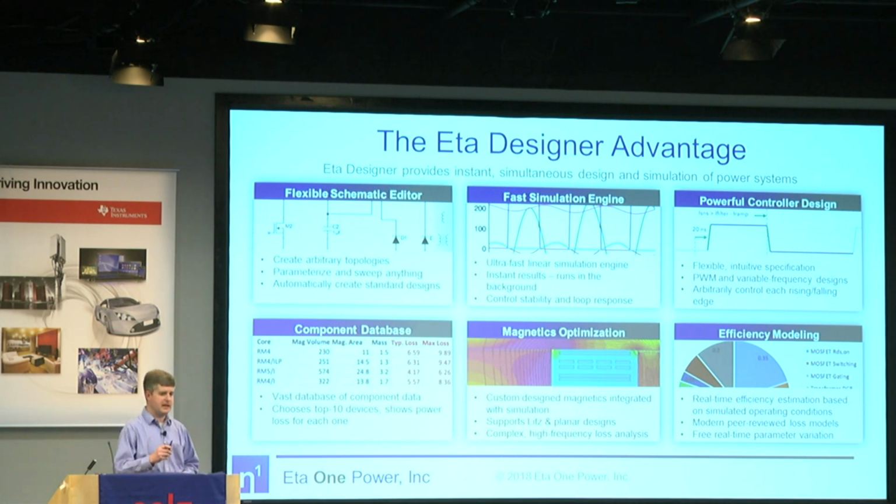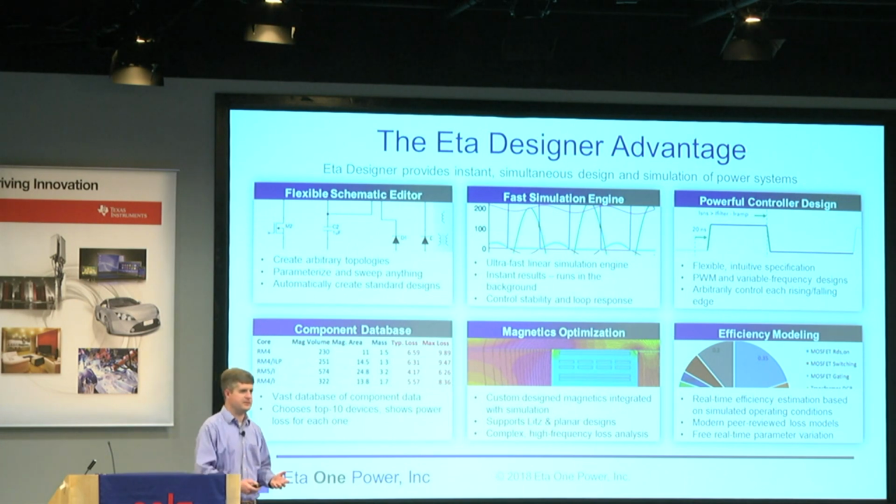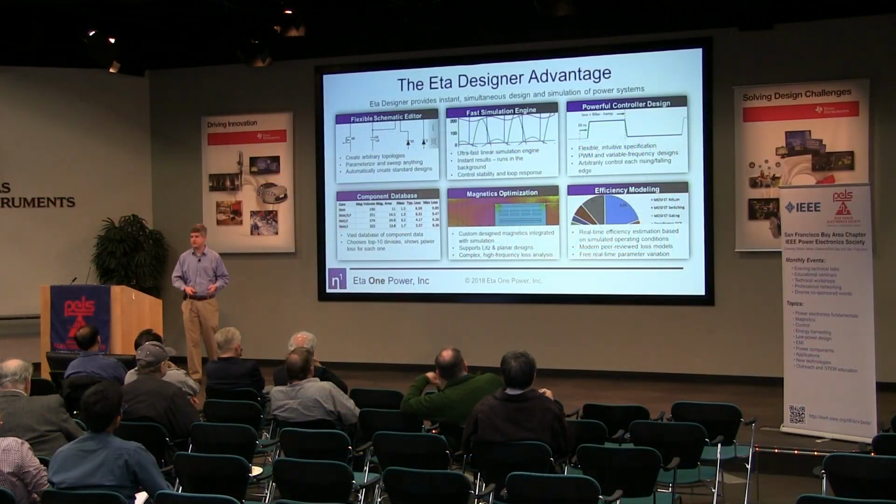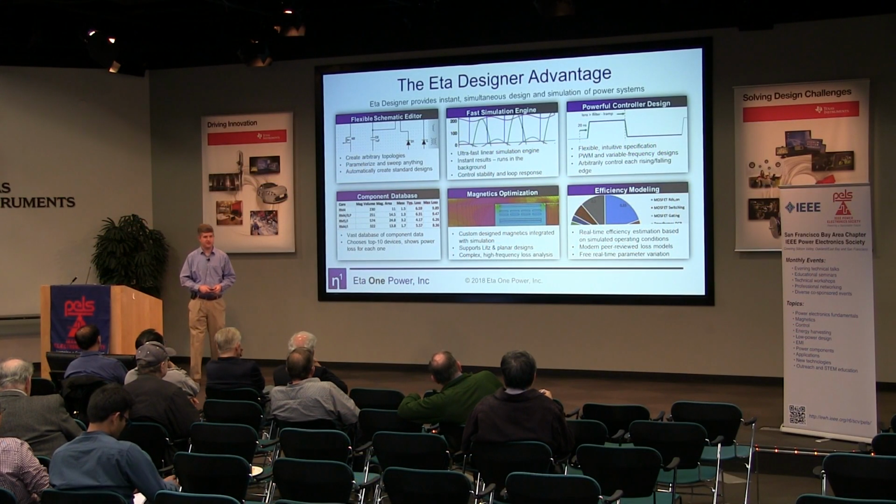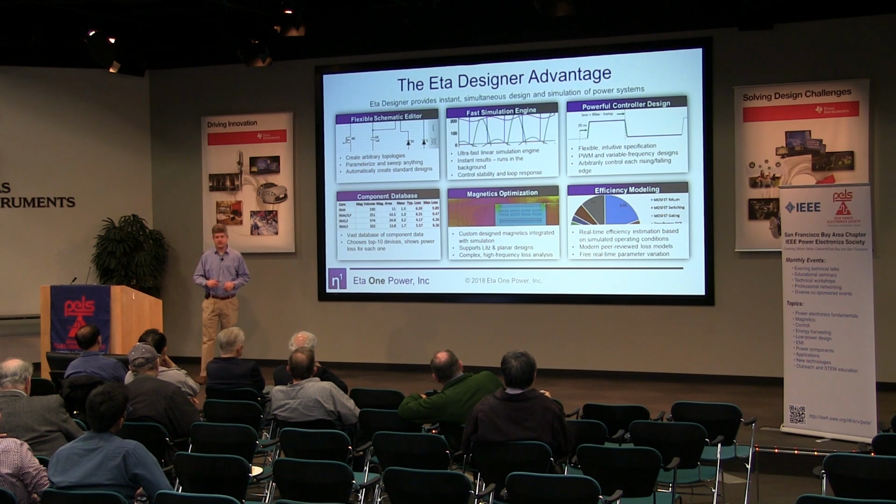We've developed a controller design such that you can come up with a control for the topology. You can come up with a switching waveform, either straightforward PWM or something very complicated with variable frequency with ZVS or ZCS, zero voltage switching, zero current switching, sensing, current mode control, all that stuff very easily. I won't be going into too much of this, but just to give you a background of what the basis is.